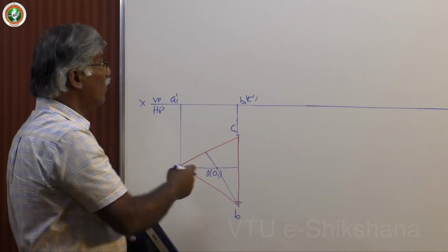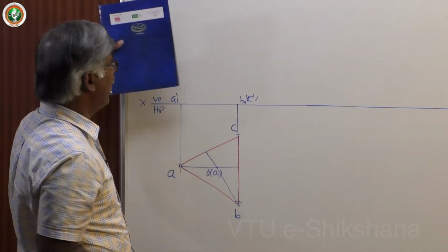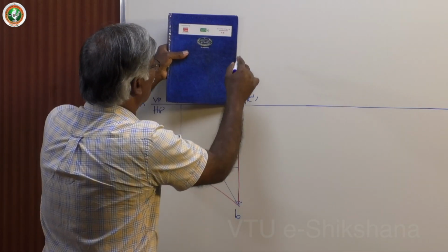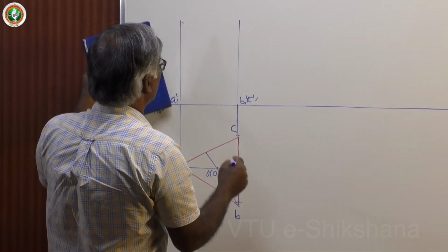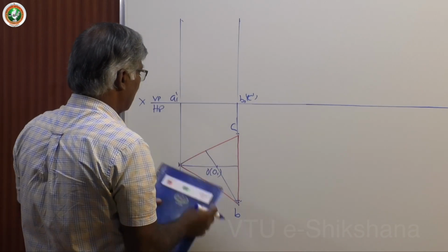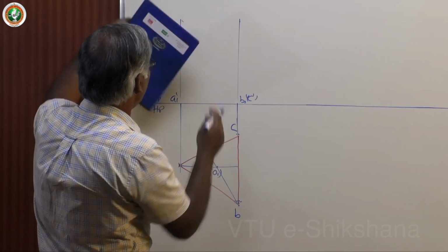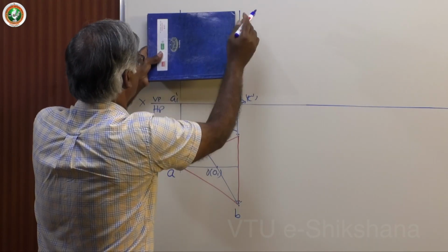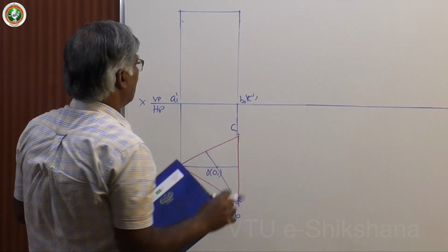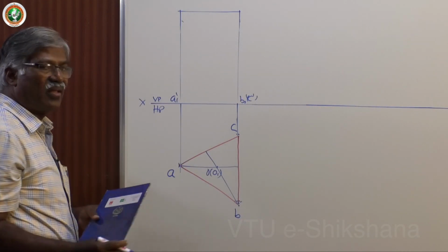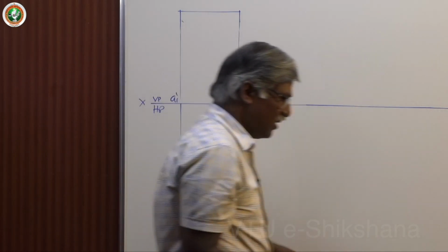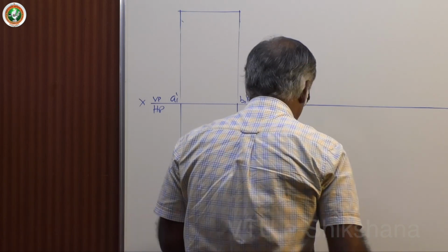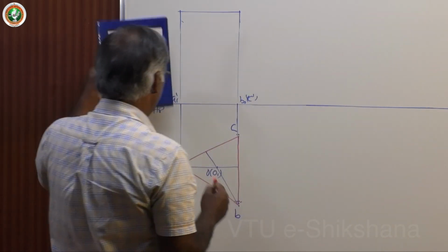Base edges. Now you take the height as 65. Okay. Now draw this projection from this and take 65 as the reference. Okay, assume that I have taken 65. Now what are the lines to be darkened? It is easy. Darken the lines which are visible first. A1 is visible.